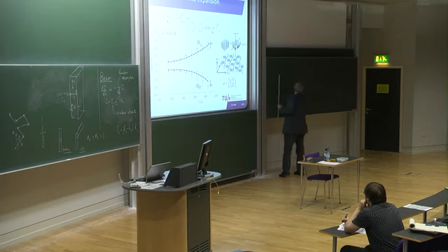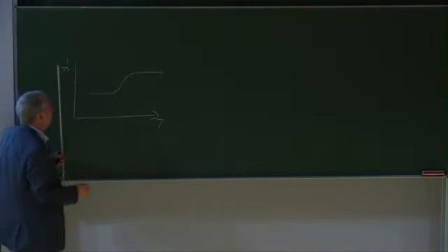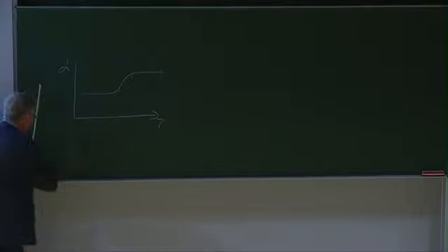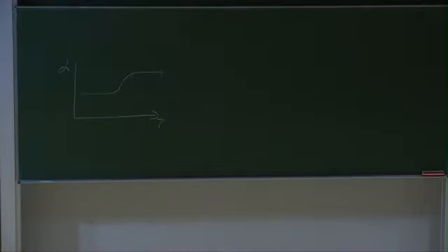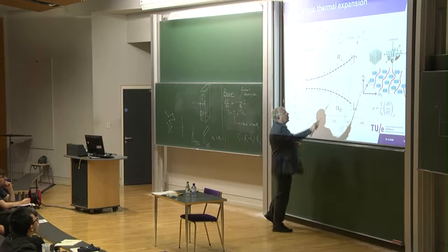So if you plot the thermal expansion of a normal isotropic polymer versus temperature, then you normally see a behavior like this. This is the thermal expansion below the glass transition temperature. This is the thermal expansion above the glass transition. So this is a glassy state, this is an elastomeric state, and of course you have a transition area. Well, our materials behave very, very differently. What you see here is that at low temperatures, you already have a difference in thermal expansion just because during heating you go from a highly ordered state to a somewhat less ordered state.